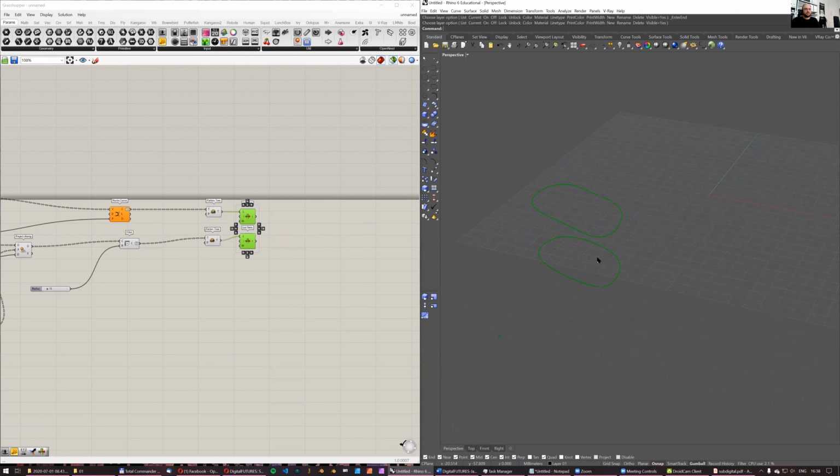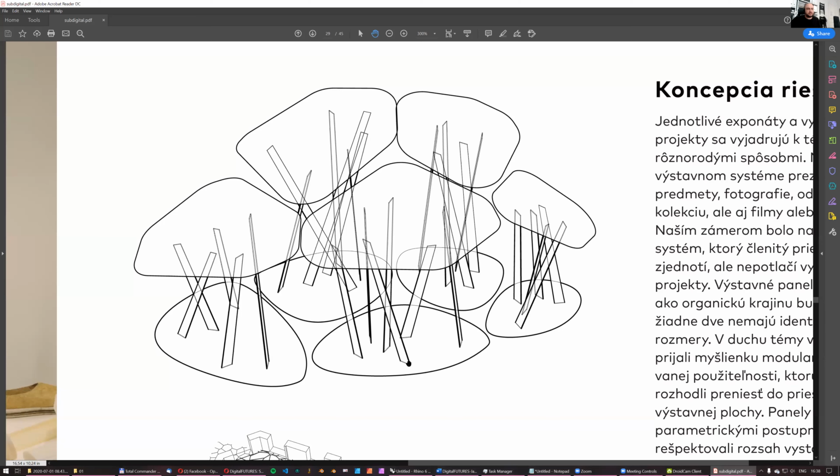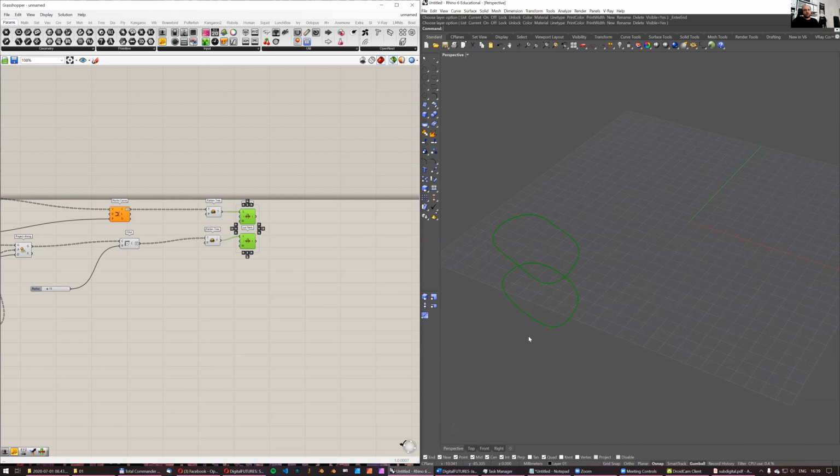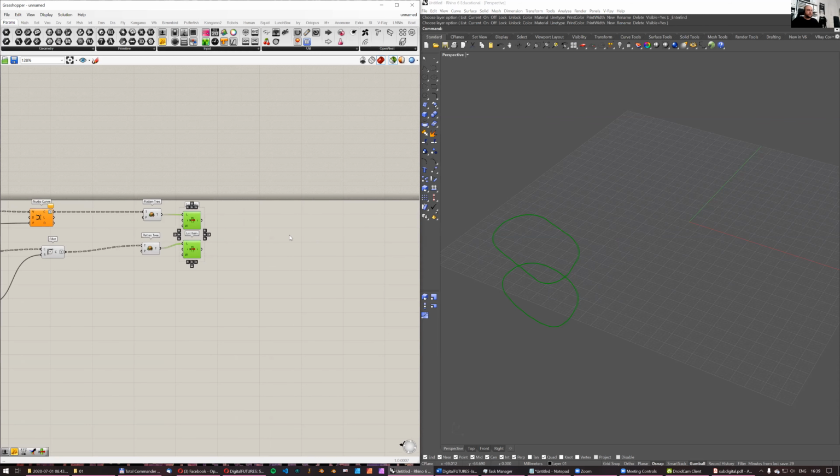So now how can I actually create those legs? Well, the leg has to be flat. And the leg also has a fixed length here and a fixed length here. In fact, this was 7 centimeters, this was 5 centimeters, and it applied to every single one of them, no matter how long it was. Always the bottom edge was 7 centimeters, the top edge was 5 centimeters. So I need to somehow create some edges. And the easiest thing would be to have some plane and cut these things with a plane.